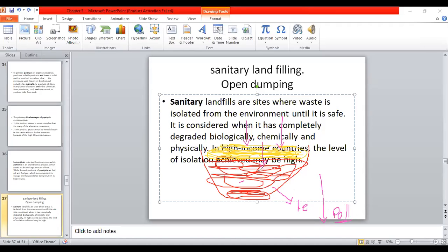At the same time, it is getting dumped. When this material is getting decomposed, the reduction of volume is also being performed. Because of reduction of volume, if it is filled up to this level, it may go down up to this. It will convert into a big pit over here, is it? And this area is completely banned for any activity, is it? So these problems were observed during landfilling, and definitely there is also the emission of air pollutants.